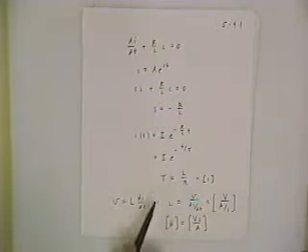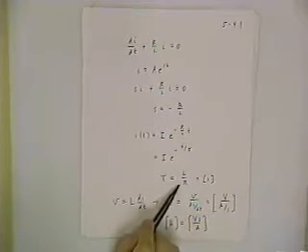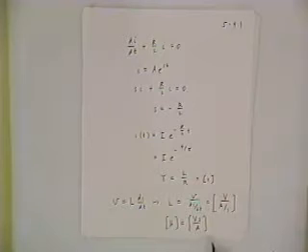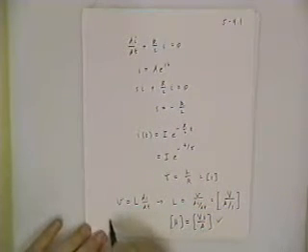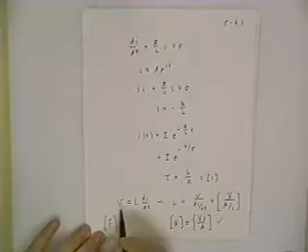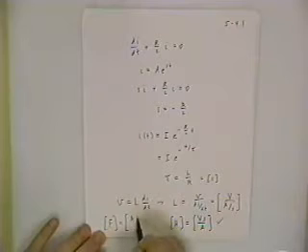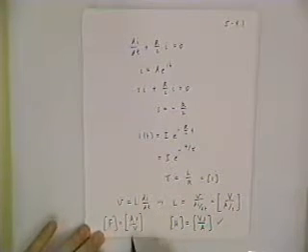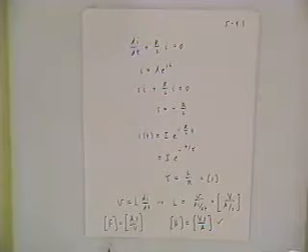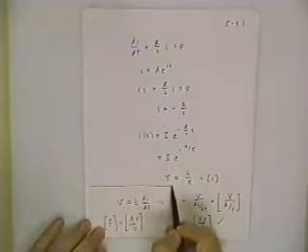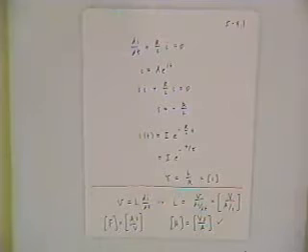And now if we put Henrys up here, volt seconds per amp divided by volts per amp gives you units of seconds. This is going to possibly be very useful in checking the dimensional consistencies, making sure that you haven't made any mistakes in your calculations. Similar expression for a farad. You can go through the same kind of analysis with the model for the capacitor and convince yourself that a farad is an amp second per volt. And that's why R times C gives you units of seconds for time constant. That bit is just an aside about the units.